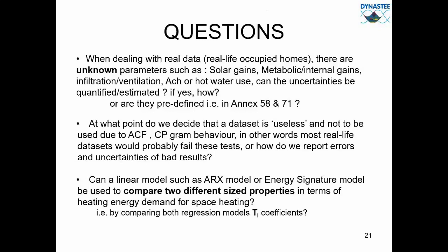You can measure CO2 concentrations, relative humidity, or even combine them with techniques for estimating how many occupants you have in a thermal zone by artificial vision analysis.